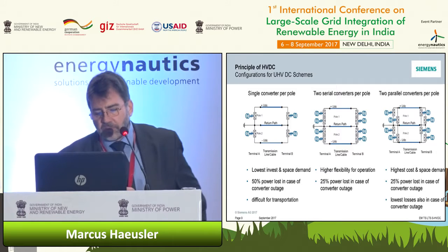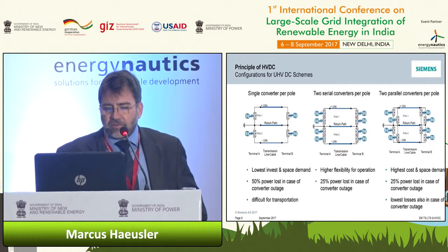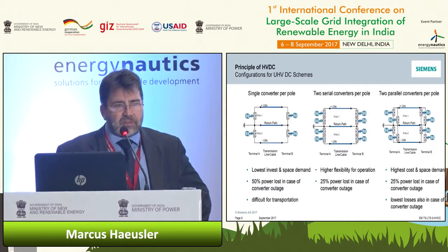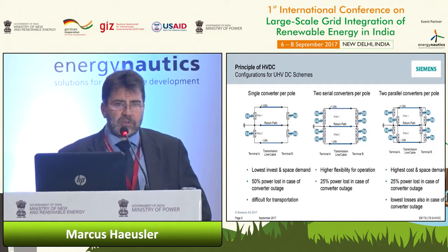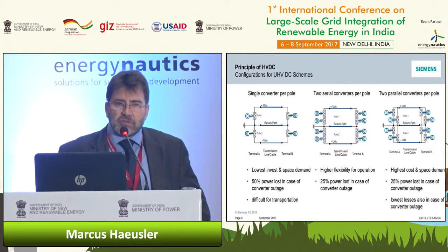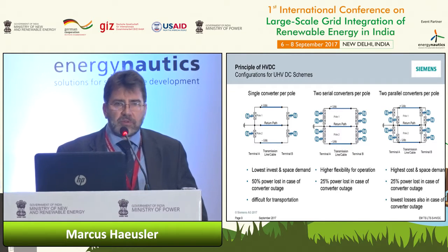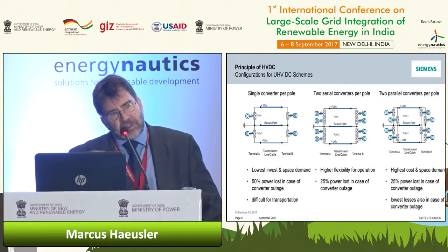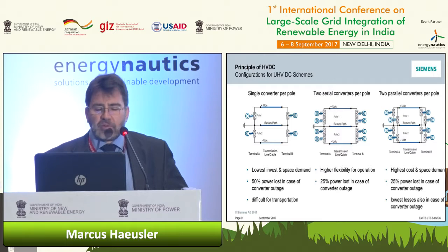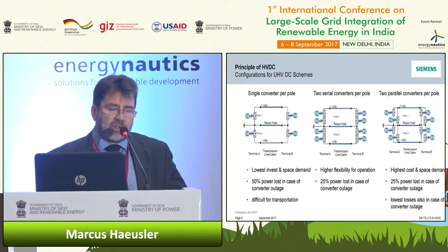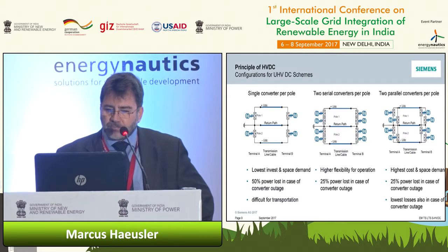And it's, of course, a little bit more expensive compared to the left-hand scheme. However, there was also one practical reason to choose such a topology, which is that the large transformers could not be transported to site. As I mentioned, this is a hilly area, so transportation limitation was also forcing us to divide the power into smaller units.